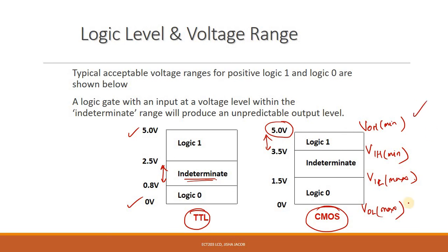Of course, VOH and VOL are the voltages that we are producing for logic high and logic low. Therefore, it has to be perfect. There is no noise expected, and therefore it will be a perfect 5 and a 0, according to the supply that we are giving.